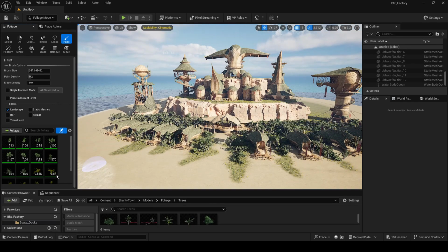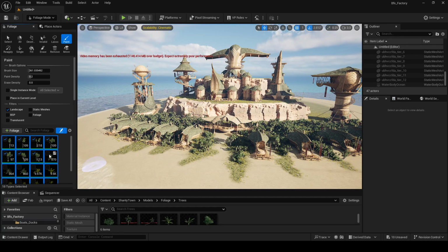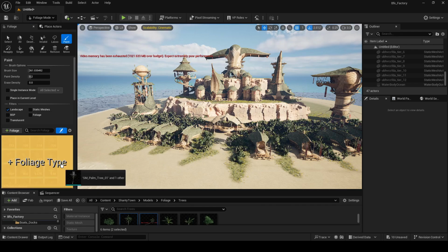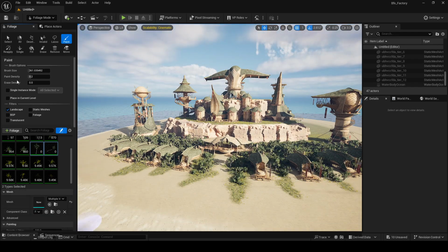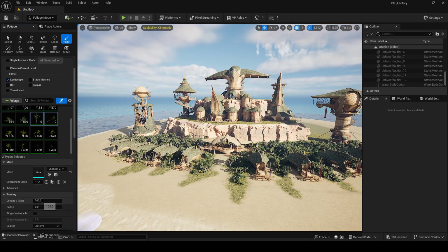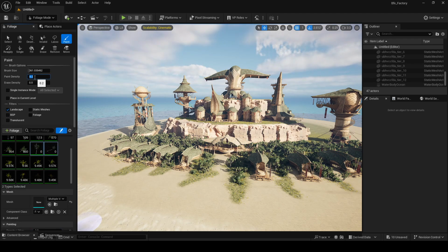Before that, let's select this all to make sure nothing is selected here now. Just drag and drop these 2. You can see this is selected, and for the coconut trees, I don't want any high density, just type 2 in the density, and this will also be 0.1, and let's apply just here and there.